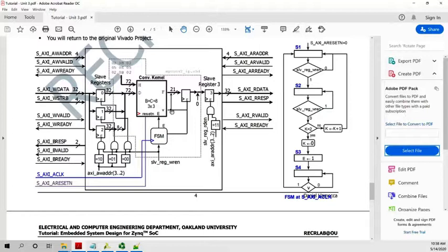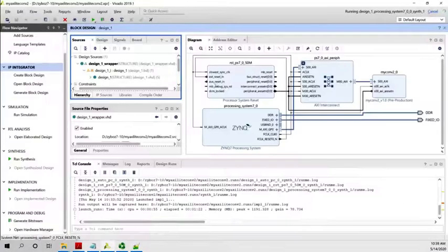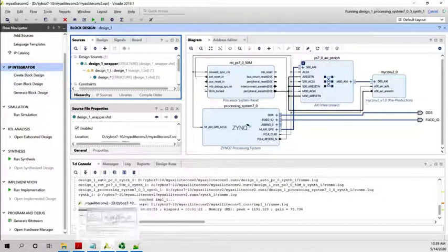So this is being read already by this register. I have 32 bits ready. That's what I am actually reading in my test bench, the 32 bits. But it happens that bit number 20 of these 32 bits is actually V. So I have to check that this V is actually 1 to know that the data here is valid. So that's why I have here a small loop in hardware. Let me see. Sorry, in software.